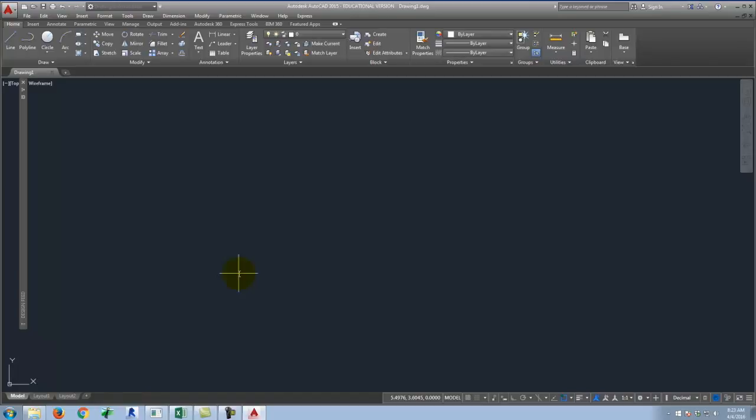Okay. AutoCAD works the same way in that it has a coordinate system in x and y that underlies everything we draw. So when I'm typing in a coordinate, I can specify, say, I wanted to start a line at point 0, 0, which would be right there at the origin. I can type in 0, 0, and end up with a point that starts at the origin.